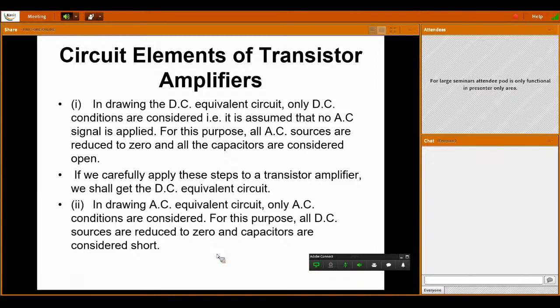So now, while you are doing your biasing circuit, we have completed our DC analysis, how to draw the DC load line. The AC load line is also drawn by just grounding your DC signal source and by calculating the AC currents which are flowing through that transistor, and the voltages due to the applied AC signal input.